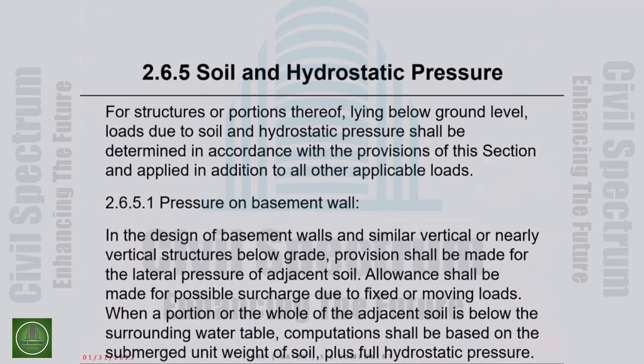Okay, I think this is the last load that we will talk about. Soil and hydrostatic pressure. So for structures or portions thereof lying below ground level, loads due to soil and hydrostatic pressure shall be determined in accordance with the provisions of this section and applied in addition to all other applicable loads.